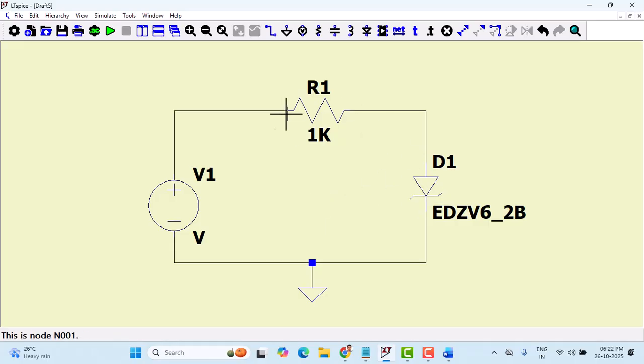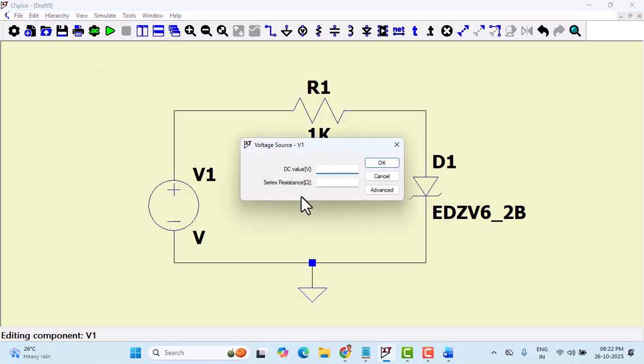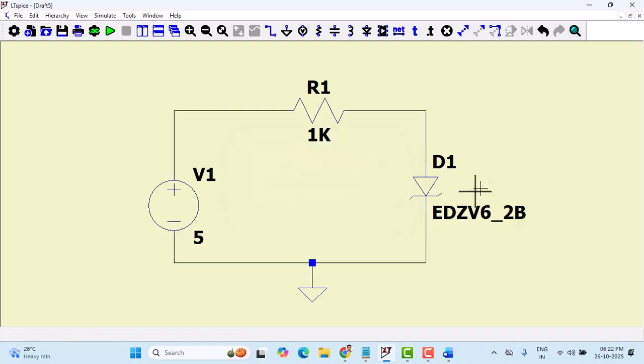Yes. So now I'm plotting the Zener diode characteristics. Therefore, I have changed to Zener diode. Here I will change V1 to 5 volts. Later on, I will make this as a sweep to a bigger range. Initially, I will make DC voltage 5 volts. V1 as 5 volts. Is it clear to you, all of you? Yes, sir. Do you find any difficulty in this one now? So just placing components and changing its value, that's all, after doing the connection.